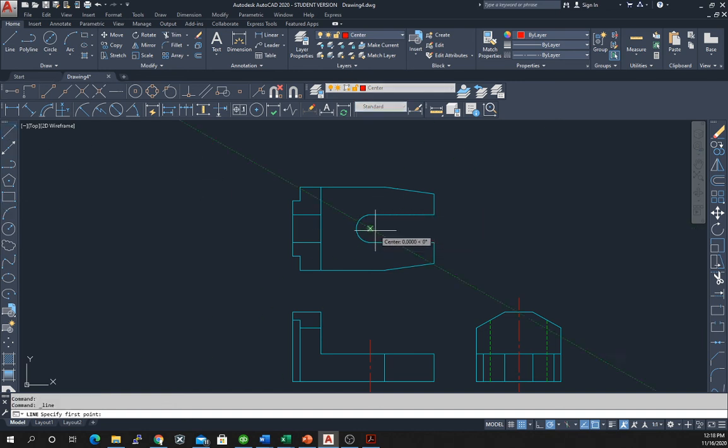Now we could actually try to do a center line using the center line center mark, but in this case it's easier to just do it manually. So we can just start there, bring a center line up, and then do the same thing. Reference from here, pull the tracking line out, start on one end, bring it to the other side, and end.